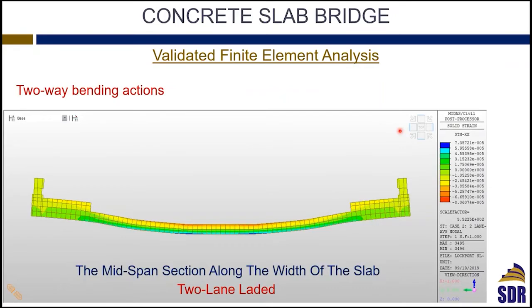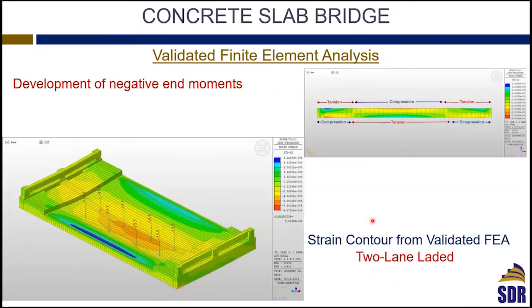One of the most important things that we have also learned about reinforced concrete slab spans is that once you have the barriers in place, which are an integral part of the slab, going back to the picture before, those barriers actually act as inverted beams. This is a common thing that's sometimes used in structured buildings when you have to have a beam and you cannot drop it under the slab. If it's an end floor, you can invert your beam. So basically the slab is hanging from your beam, not sitting on top of your beam.